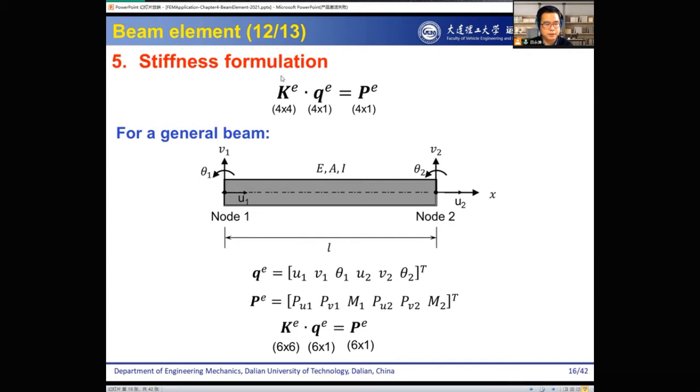But if you notice the stiffness equation, we have the external node force matrix, and the external node force matrix only considers the force at the node. So if you have an external force which is not on the node, you are not able to consider this force in the stiffness matrix. If you don't consider this in the stiffness matrix, you are not taking into account the effect of this force.